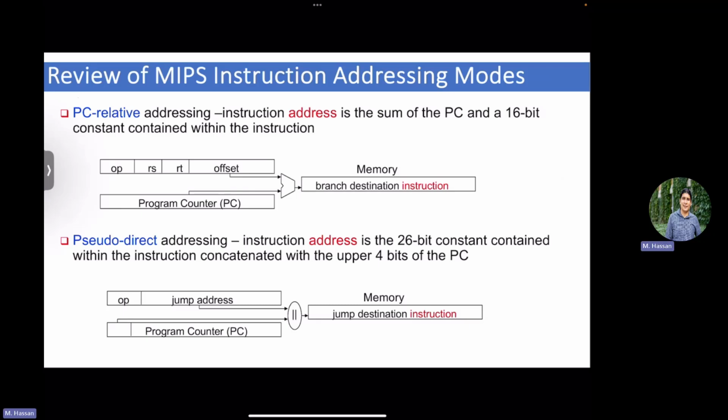The RISC mindset from the beginning is you want to simplify your hardware as much as you can. Why do I want to simplify it? To make it scalable and fast, right? The simpler you are, the more regular you are, which means you can scale easily, and the faster you can execute things without a lot of complex logic, right?